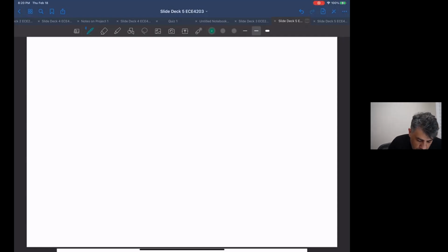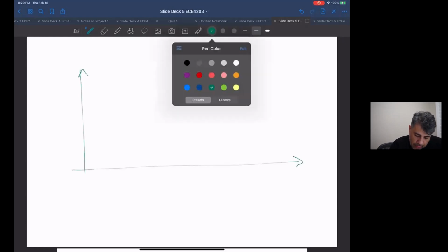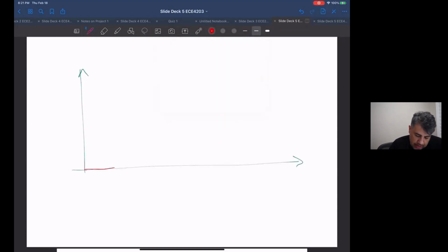So the prop delays have to do with delays from input to output. Rise and fall time delays have to do with just the output transitioning. So the prop delay rise is like this. Say this is my 1.8 volts, I don't know what you have, but let's say this is 1.8 volts.